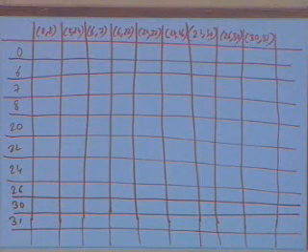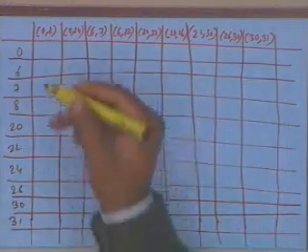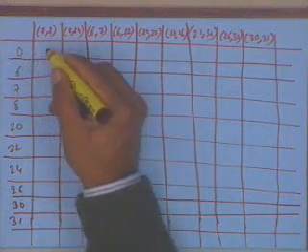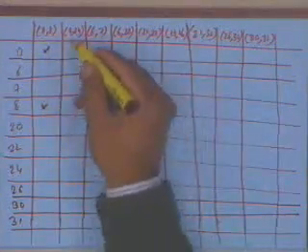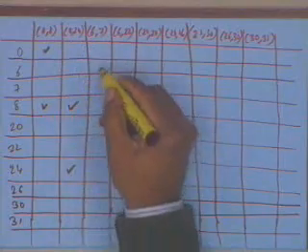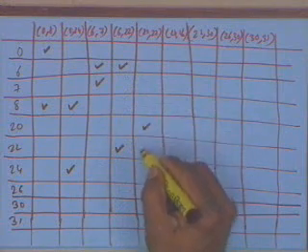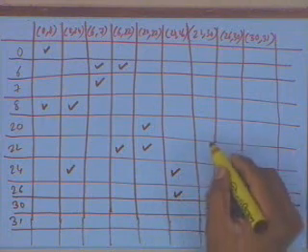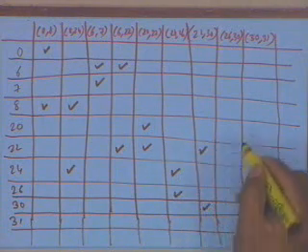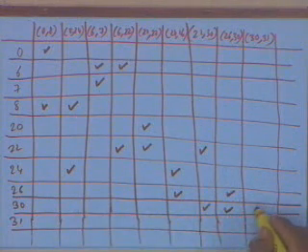Okay, what it consists of is columns. Each column corresponds to a prime implicant, and each row corresponds to a minterm. And we basically now say that whichever it's, let's say 0-8 covers these two, 8-24 covers these two, 6-7 covers these, 6-22 covers, 20-22 covers this, 24-26 covers this, 22-30 covers this, 26-30, 30-31 covers this.